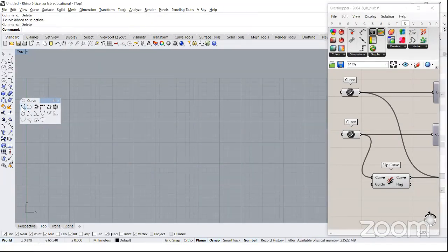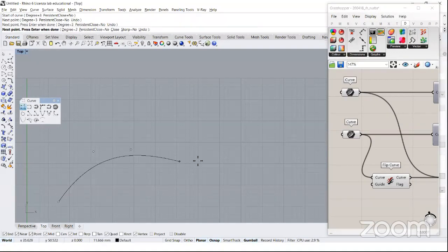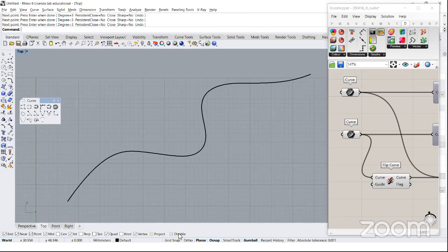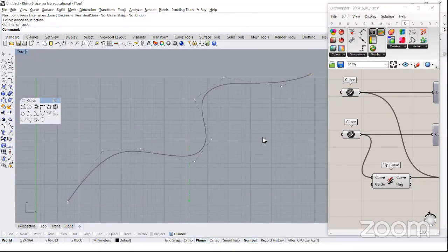So I do recommend that you eventually get familiar with the way the control point works. For example, let's say that I have an original line from the sketch, which is this one, and I want to trace this with another line. This is the pencil sketch that we are seeing. Eventually, I'm going to lock it, so it becomes gray, and I want to trace another line. I won't use this. I prefer to use this because this gives me access to a better control later.